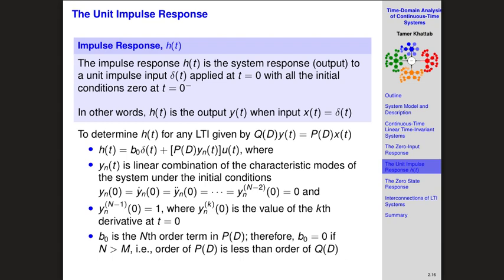Okay, so now it's down to an important part. In order for me, when I'm dealing with a linear time invariant system, to be able to calculate the output for any given input, I need, first of all, to know the input. That's going to be given to me. Someone is going to ask me, calculate the output for example, a unit step. Calculate the output of this system for an exponential, rising or falling. Calculate the output for a cosine. So definitely to calculate the output for a given input, the input must be given, right? Now it's down to how can I figure out the impulse response, okay?